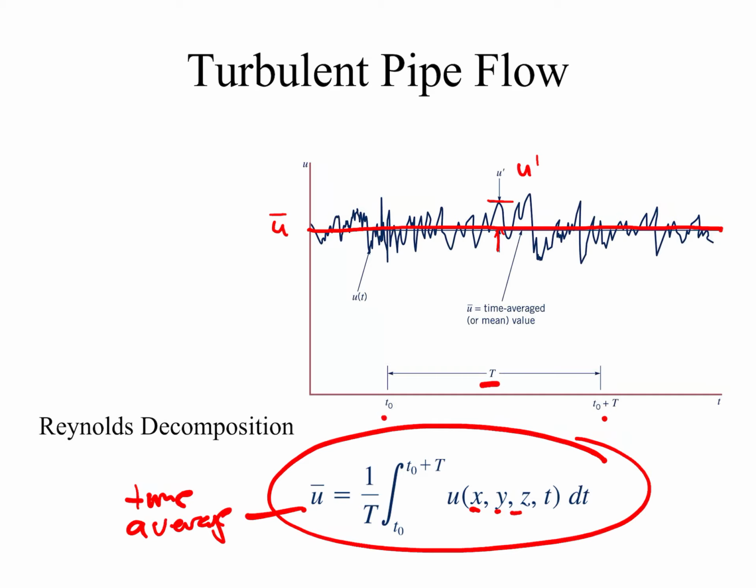And that is one of the key points that we deal with in turbulent flow. We can't have an instantaneous velocity. It's very difficult for us to deal with that analytically or even experimentally. So typically we take these fluctuations that are associated with turbulent eddies. Each of these fluctuations that you see here is associated with eddies going past some sort of probe, say a hot wire anemometer probe, blowing across at some velocity u and mean velocity, and these eddies are causing fluctuations that have a little higher momentum or a little lower momentum in the fluid.